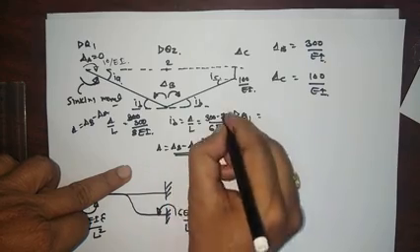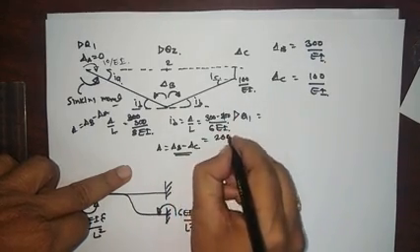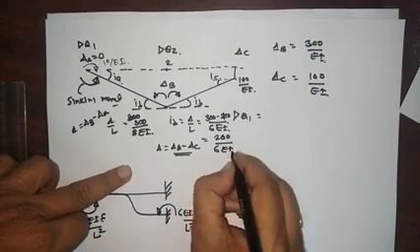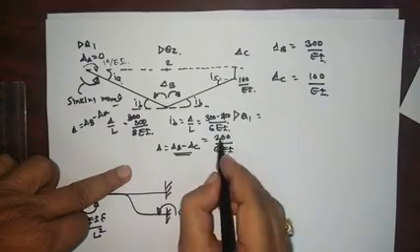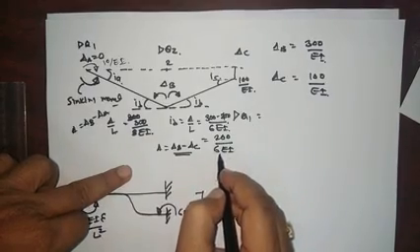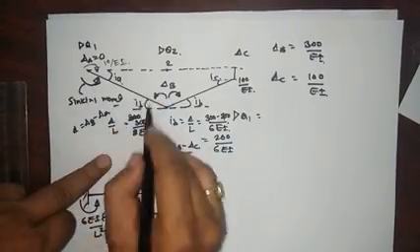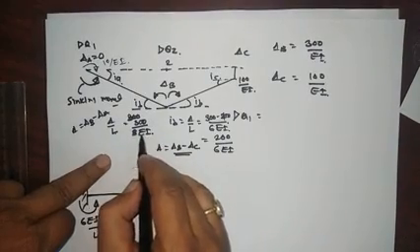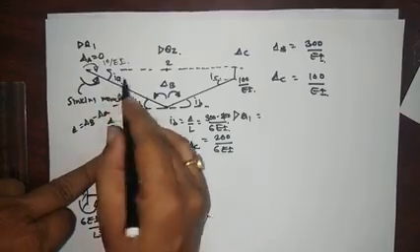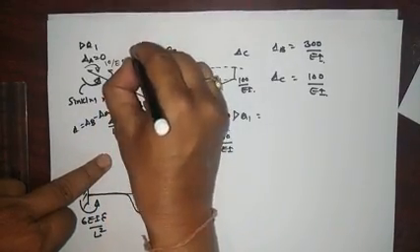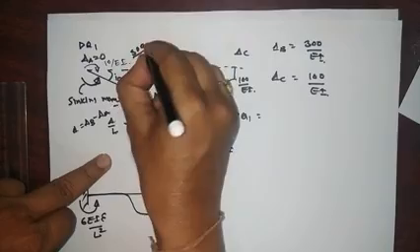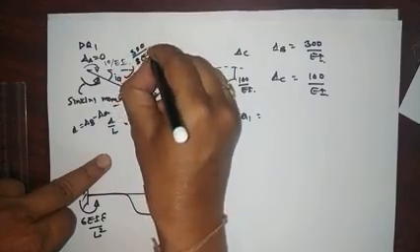So this becomes 100 upon EI, and this becomes 200 divided by 6 EI. So the slope for the BC span is 200 upon 6 EI, and the slope in the AB span is equal to 300 divided by 8 EI. Now the same is here, this is nothing but 300 divided by 8 EI.